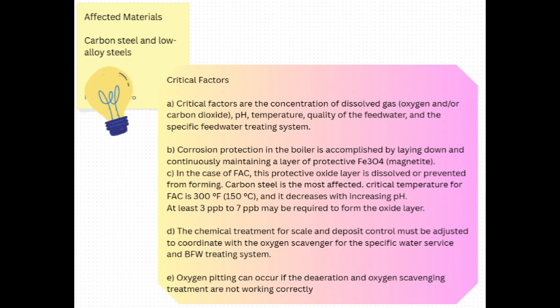Why specifically there, condensate return? Right, think about it. CO2 gets stripped out of the feed water earlier on, hopefully. It travels with the steam as a gas, no problem. But then way downstream, that steam cools and condenses back into water in the return lines. And boom, the CO2 dissolves back into that fresh condensate, makes carbonic acid right there, often where the metal isn't as well protected. And the temperature is lower. Got it. So oxygen, fast, localized pitting. CO2, slower, maybe smoother thinning or grooving, especially in condensate lines.